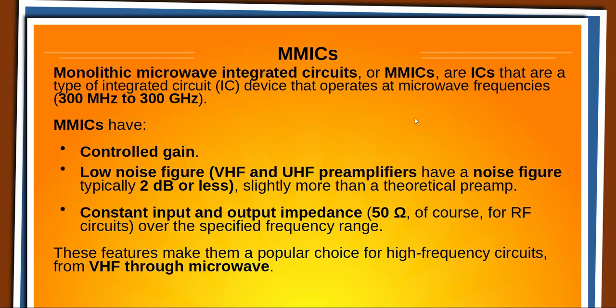Okay, so an MMIC is a special type. It was created for doing microwaves. They're also useful at HF frequencies. That radio I'm building uses those as a preamplifier in the RF stage. They're designed to operate in a 50 ohm circuit. In other words, they have 50 ohm input impedance, 50 ohm output impedance, very wide, flat frequency range to go up into as much as 300 gigahertz.